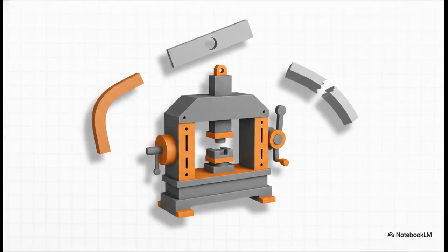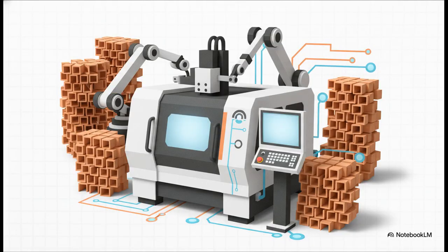But say your volume increases. Enter the mid-range hydraulic setups. These are the absolute daily workhorses for so many electrical panel builders and switchgear manufacturers. A lot of these are 3-in-1 machines, meaning they bend, punch, and cut copper or aluminum all in one compact unit. You get incredibly strong performance and high reliability, but with a highly accessible initial investment compared to the fully automated systems.